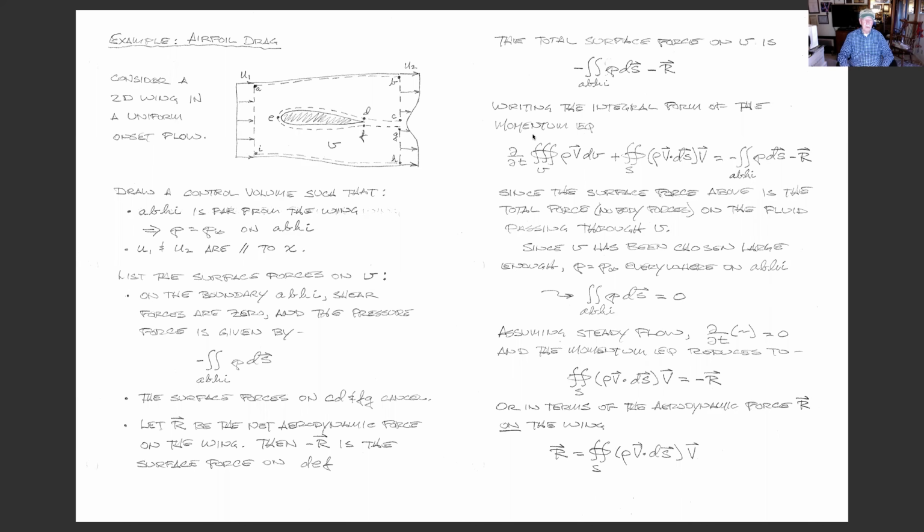Draw a control volume. And okay, you've got this flat plate with an inlet below it, right? And yes, the upstream pressure as the flow is arriving there is increased. Now it goes into the inlet, but with that increased pressure, there is flow deflected down. And now when it goes in the inlet, it's straightened out. And you do the math and there's no benefit. I mean, it's deflected down by the wing, but it's coming straight out the back of the engine.